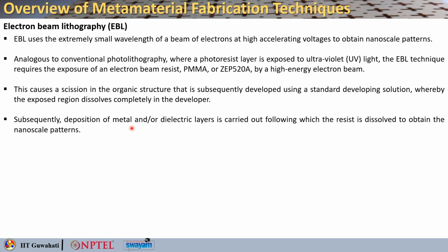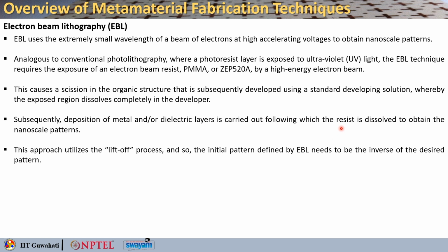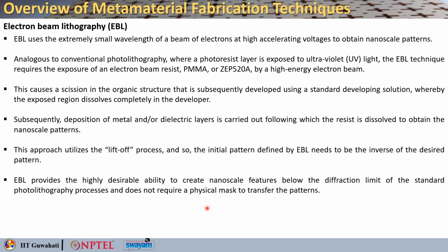Subsequently, deposition of metal and or dielectric layers is carried out, following which the resist is dissolved to obtain the nanoscale patterns. This approach utilizes the lift off process, and so the initial pattern defined by EBL needs to be the inverse of the desired pattern. EBL provides the highly desirable ability to create nanoscale features below the diffraction limit of standard photolithography processes, and it does not require a physical mask to transfer the patterns.